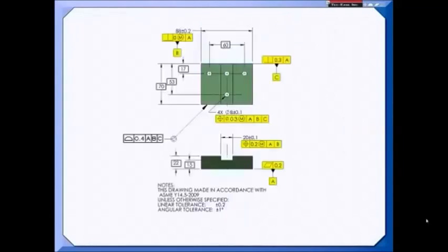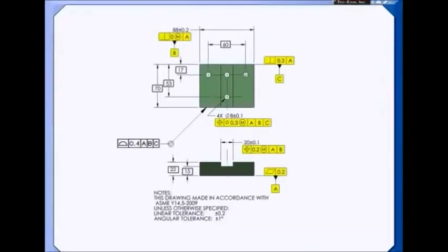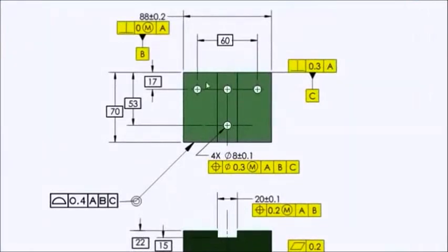In a recent tip, I had a drawing that had some dimensions that were implied centered on the datum center plane. And I had someone contact me and insist that I add half dimensions for the people who really don't know that there's this implied zero basic, and that I can imply that these dimensions, like the 88, the 60, and the 20, are implied centered.